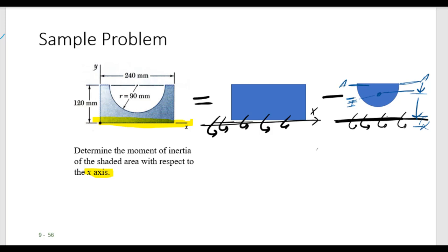So if we have the inertia around AA, which is what is in the table, and that is also related to, I'm going to call this first distance A squared. So we'll go from AA to the centroidal axis, right?